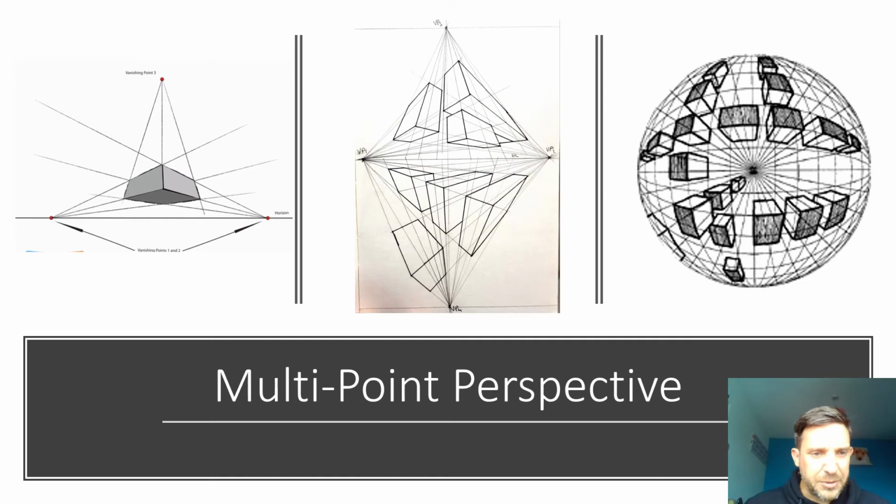The 3-point perspective drawings are pretty good because not only are you taking your 2-point perspective, your 2 vanishing points we saw in the previous slide, but we're also adding a height as well, which is what we would see in normal everyday life. So actually a 3-point perspective drawing is probably the most realistic. And if you look at it, to me, this looks like a cube that I'd find if I'm wearing a VR headset, with the perspective angles going towards those vanishing points.